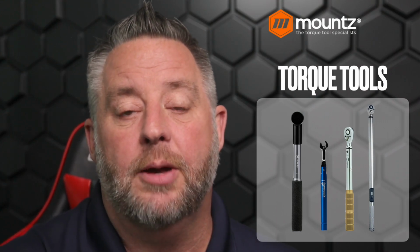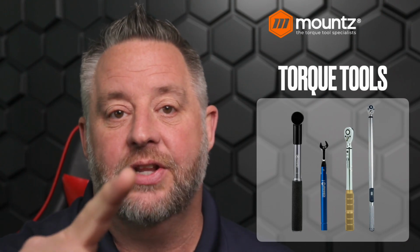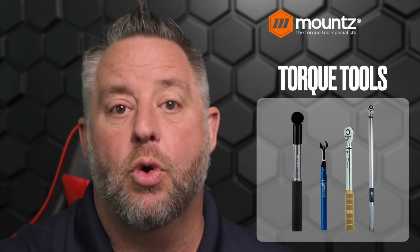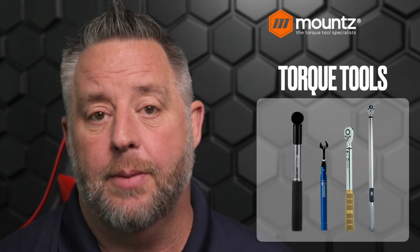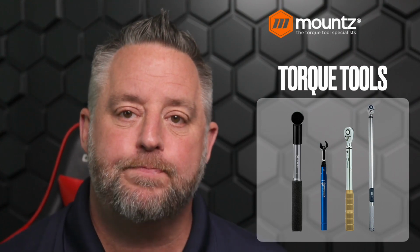That can only be achieved with the cam over style of wrench, that as that wrench is used, it simply slips and you can never over torque or never pull more torque than the cam will allow you to. So click wrenches, again, very, very popular tool that are used in the torquing process.